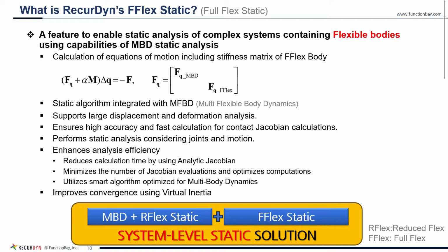So, what exactly is RecurDyn's F-flex static? It is a feature that enables static analysis for even highly complex systems that include flexible bodies, so-called F-flex bodies. Mathematically, it seems that you just need to include the stiffness matrix of the flexible body in the stiffness matrix. However, it is not that simple. If it were that simple, this calculation would have been possible with other solvers.